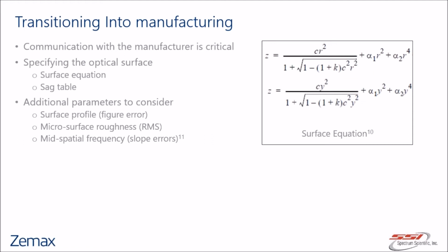And I think at this point it's really important to note that the freeform optic need only be a few fringes or a few microns of departure from the best fit radius or conic in order to be effective. It doesn't need to be a radical shape that you sometimes see in some of these presentations.